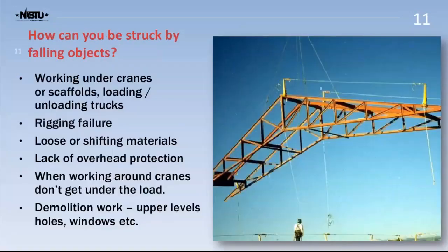First thing, cranes are often on construction sites. Almost every construction site at some point has a crane, or for sure scaffolds for access. And these, especially cranes for loading and unloading trucks, can be a source of stuff falling on you. I mean, look at that picture. Imagine if that roof system fell. If the rigging somehow collapsed, what would happen? And rigging sometimes does fail.